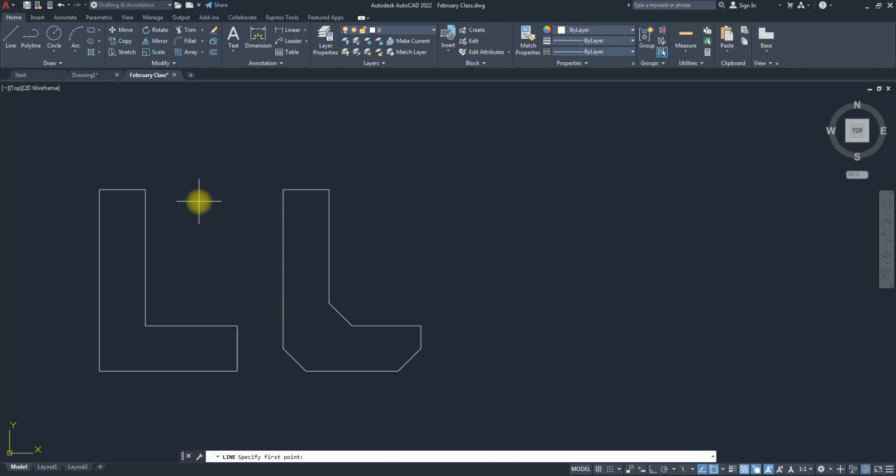That means I need to put on my auto mode, right? So I'll put on my auto mode. Once I put on my auto mode, you notice my snap and my grid are off. So I don't want to use snap here. Now, auto mode constrains it to vertical and horizontal. So if I go to this direction, I want to create the length. I know that the length is what? 8. Just move towards the direction you want to create and put the length 8. It's going to create it.